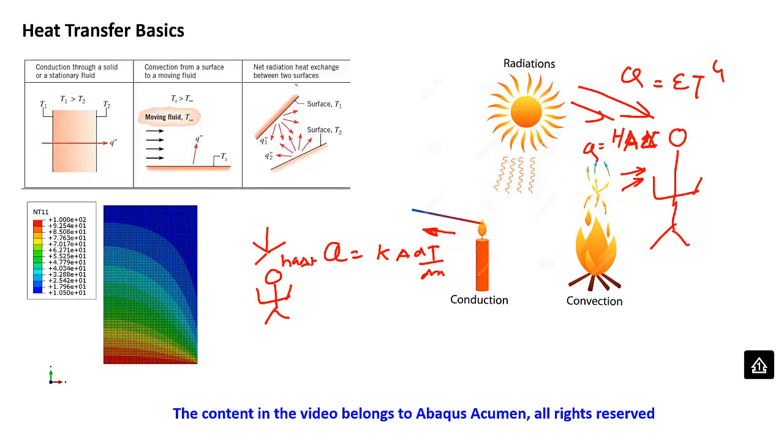And then the radiation heat transfer depends on the view factor. Suppose I put an umbrella here, so my view factor is different, so you will not get this heat transfer. Radiation heat transfer is multiplied by the view factor. So you have different options, surface 1, surface 2, how is the view factor, and the emissivity part.